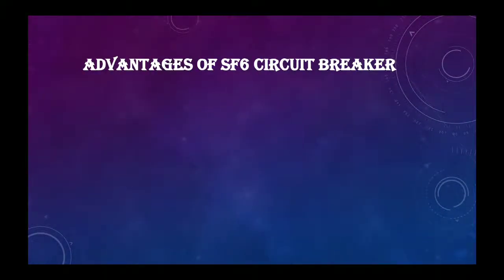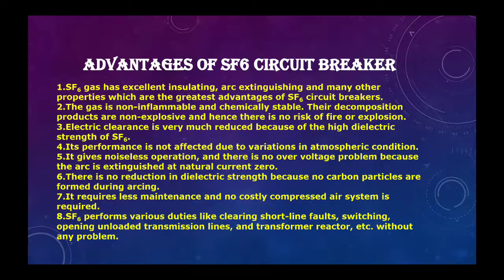Now the next slide is the advantages of the SF6 circuit breaker. Number 1, SF6 gas has excellent insulating property. That means it has great dielectric strength, arc extinguishing, and many other properties which are the greatest advantage of the SF6 circuit breaker. Number 2, the gas is non-inflammable, so there is a low risk of fire, and it is chemically stable. Its decomposition products are non-explosive, hence there is no risk of fire or explosion.